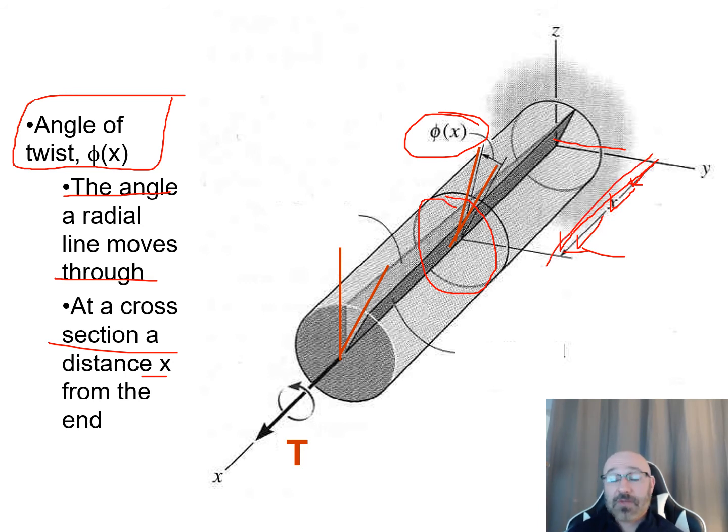So again, this is where we talk about the importance of grid sensitivity and our mesh refinement as we're looking at this. If we only look at 5 different sections along here, we may not get all the different information. So then we go to 10, then we go to 20. So we want to eventually get to an infinite number of sections along there, or get to a point where we don't see any changes in our stress or changes in individual sections in between these different layers, or minimal changes within those as we refine our grid.